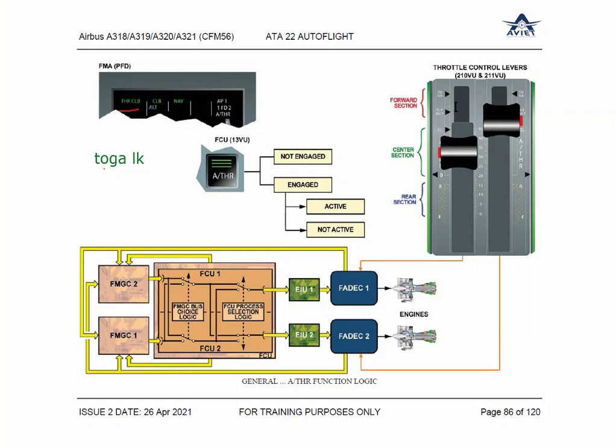Yes, there will be a big jump. So that is the function. The thrust will reduce slowly from TOGA to the lever position, wherever it is. It may be here also. Right? The lever can be here, here, or anywhere. So the thrust will slowly reduce to the lever position. I hope this is clear.